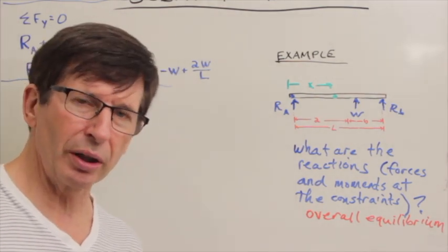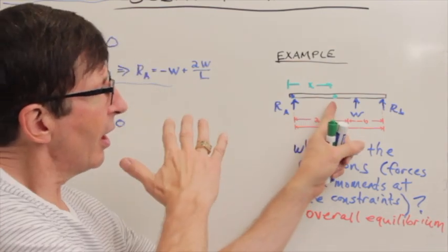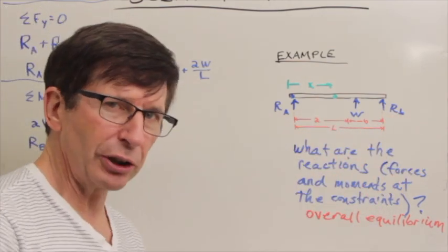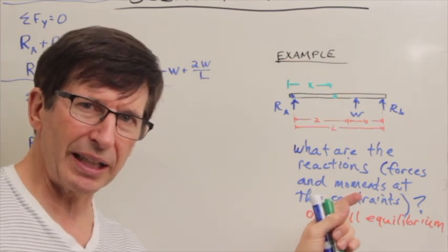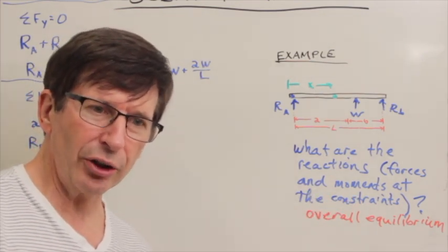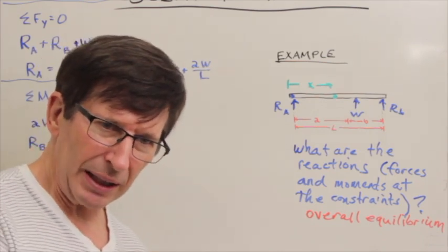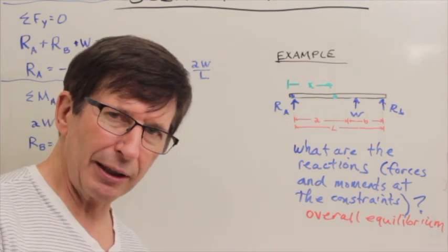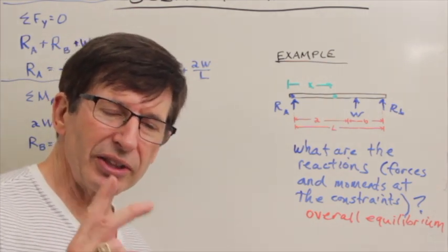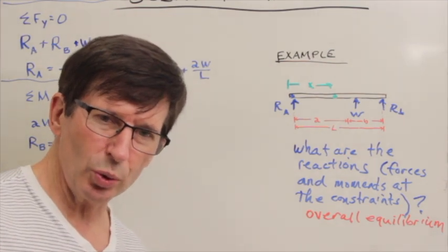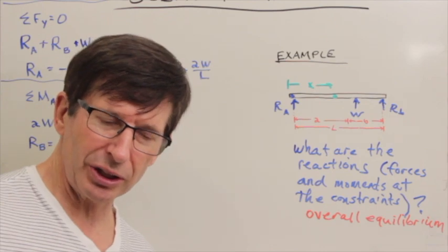And in the textbook, there are two ways of coming up with this computation of the distribution of forces and bending moments down the beam. Either we do the intuitive approach, cut the beam, write equilibrium at an arbitrary point, and write our equation. The second way is to use a technique called singularity functions.